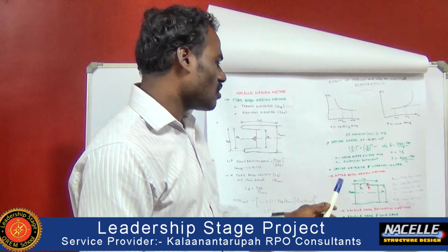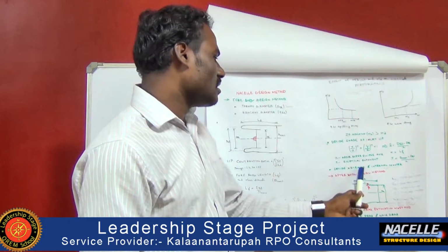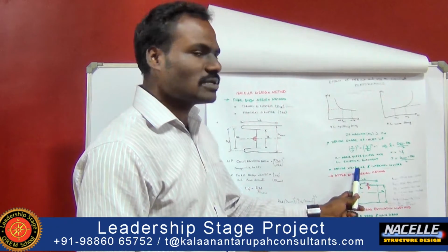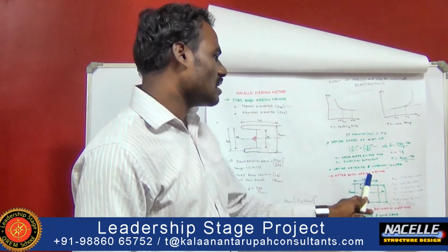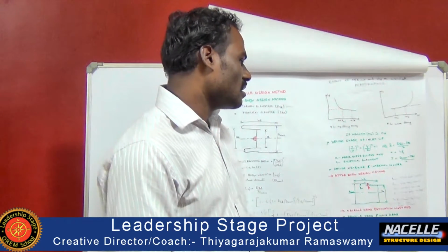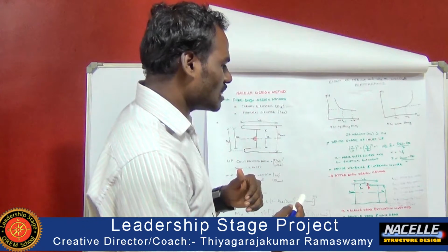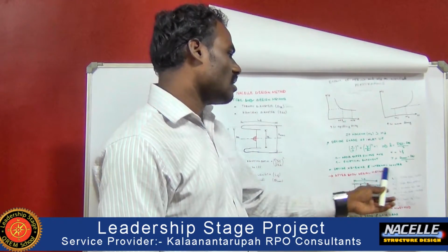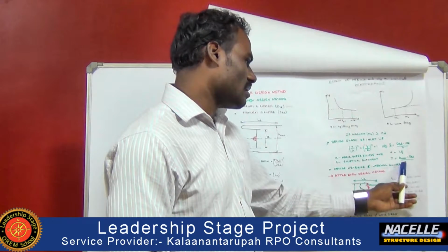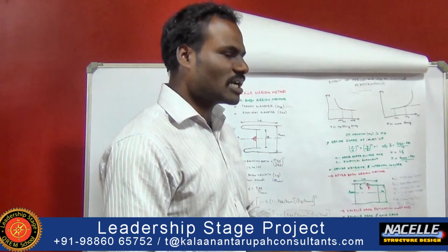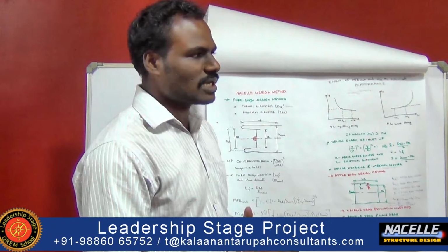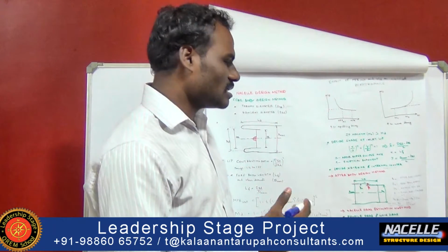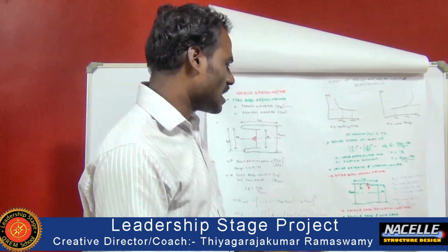So we have to concentrate more on the exterior contour, which results in a better surface finish, whereas the internal contour, here it is the portion which starts from the lip to the throat of the fan, is being calculated with respect to the better surface finish, which will help us in reducing the drag of the nacelle as well as the aircraft.